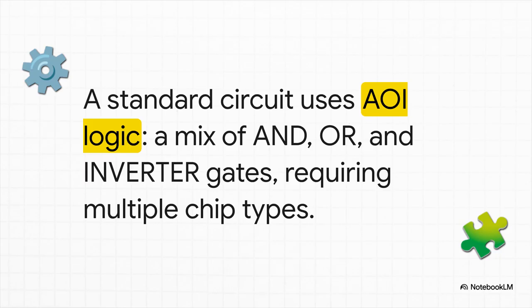To build this thing the old way, you'd have to go out and buy three different kinds of chips. Yup. You'd need one chip type that has your NOT gates on it, a different chip for your AND gates, and a third one for your OR gates. That's three separate components you've got to manage and put on your circuit board.